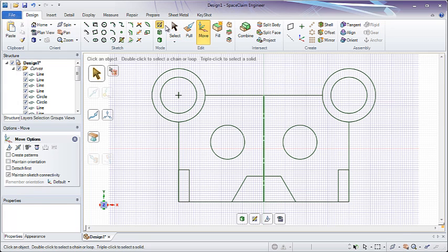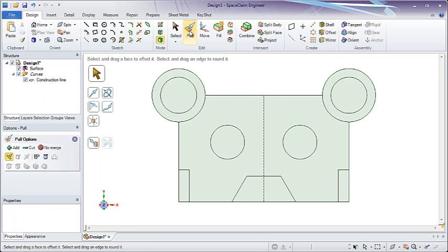And when we're going from sketch to 3D, all of the lines and curves will form surfaces provided they form closed boundaries. For instance, this will be a closed boundary versus a line sticking off into space. And you'll also notice the duplicate edges and the lines we've created are not important. These will create just one single edge in 3D, which again, I can go to by either clicking the 3D mode button or Pull.